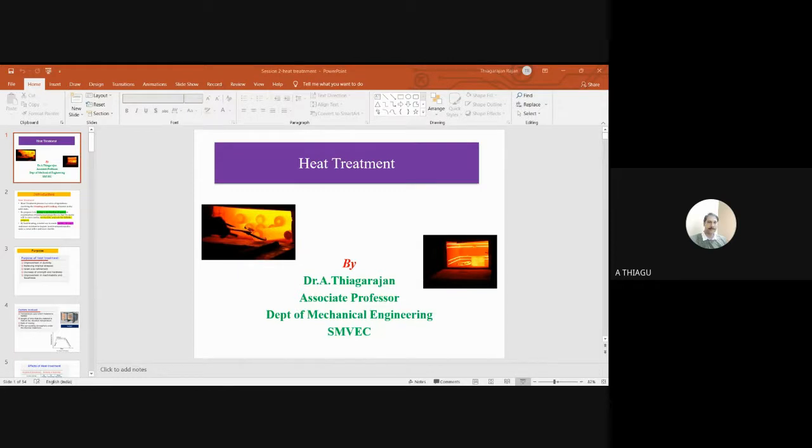So this is the image. I think you have done this practically in your first year in your metal testing or metallurgy lab. What I'm going to do is take the steel sample. The sample should be heated to 850 degrees for 3 hours in the furnace. After that, I position it in the Jominy setup. This is the holding frame where I position my sample, and at the bottom I have